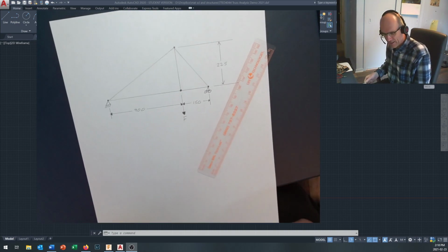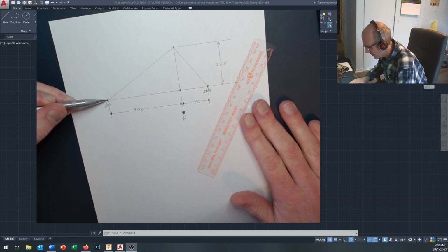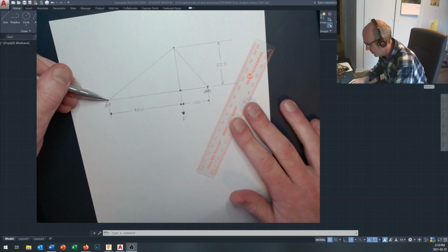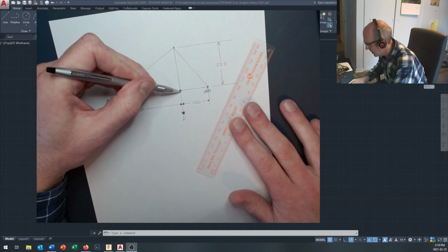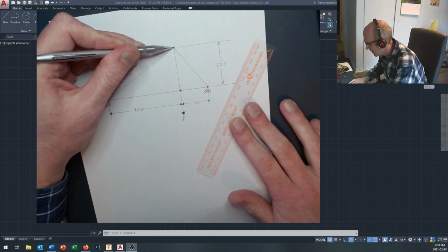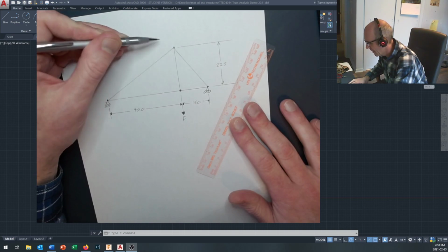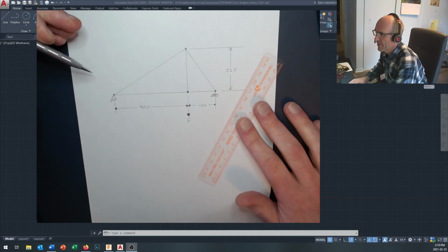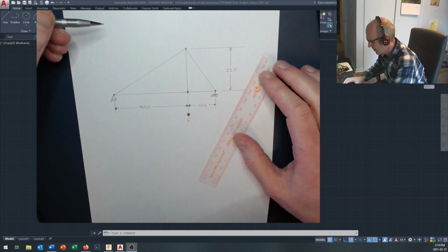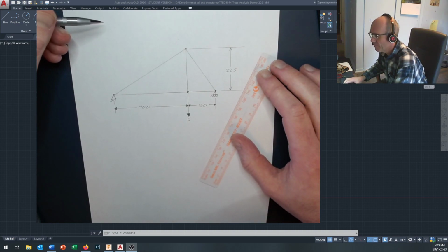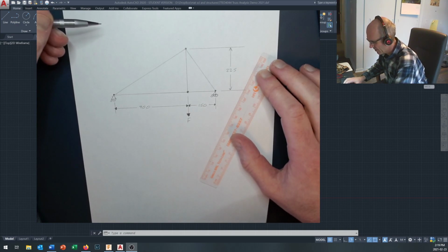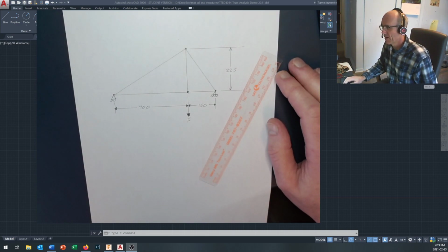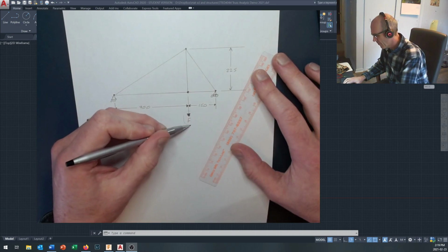So anyway, let's take a quick look right here, and we know some things about this truss. It's required to be 400 millimeters from this node to the force, required to be 150 millimeters right here. And as I was just saying, in my design, it looked like I could get about 225 millimeters tall and still be able to flip the truss over and make a second copy of it up there. Could probably go a little bit taller than that. I'm not 100% convinced that I should, and even shorter than this might be better. I really don't know right now what the optimal truss design is going to be. However, I do know that I can do a few calculations on here to help me figure out what's going on at the truss.